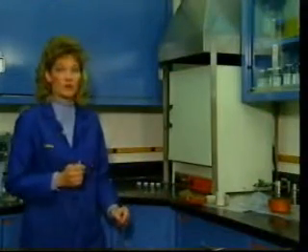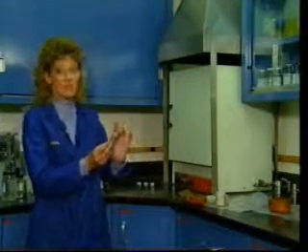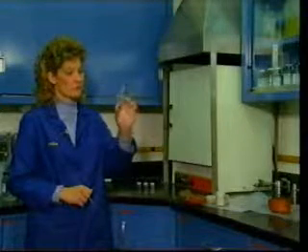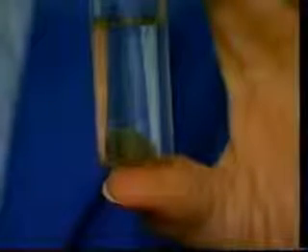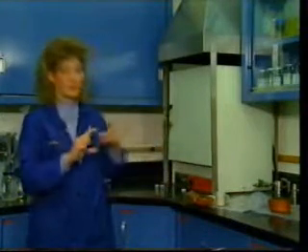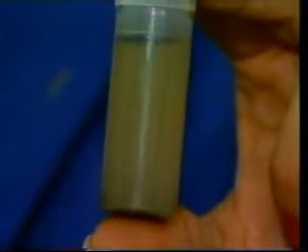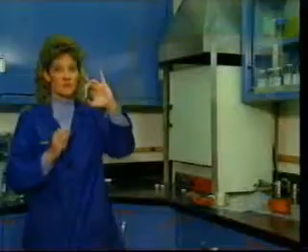A quick and easy way to determine this, one of the methods that we use most frequently, is a disassociation test where we'll soak this sample in different fluids. For example, this is bland oil. When the well is first put on production, that's basically what it'll see, oil production. As you can see here, this sample has stayed associated and has not fallen apart. However, that's not the case with water production. As the well depletes and the water production increases, this is the kind of scenario you're going to see out of this sample. This was also consolidated when we started, but it's totally disassociated at this point in time.